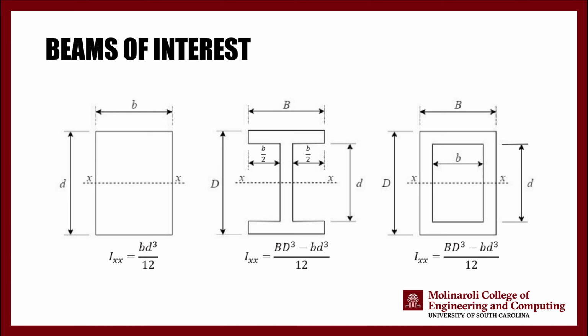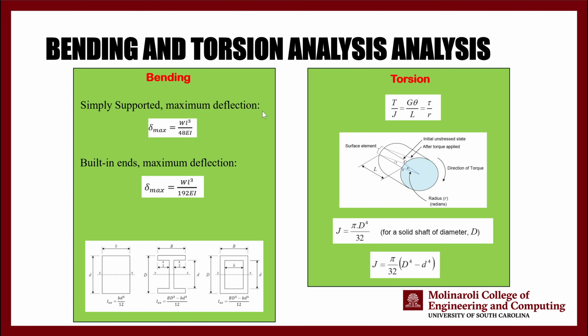Everything else, but again, material that we use in these beams is going to be the same. So the idea is, because of this moment of inertia, you're going to experience different deflections, but at the end of the day, you should calculate the same modulus of elasticity for all of these beams, because these are the same beam material. Okay, so what type of analysis should we do?